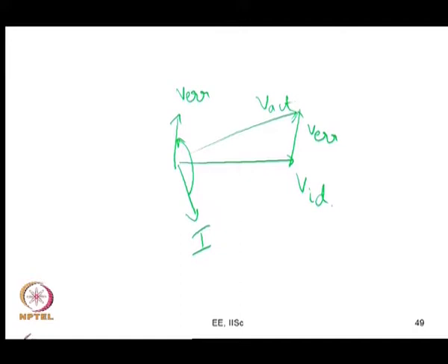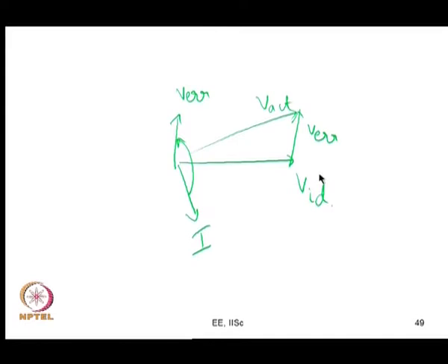What happens is there is a difference in these voltages V actual and V ideal, so this can actually be seen as an IR drop. In induction motor drives this can be seen as some additional stator resistance, and when the stator resistance is high it causes instability. Though I have not discussed it in this module, dead time also has the effect of increasing light load instability in induction motor drives, which you can find in certain papers. If you compensate for dead time, you can handle light load instability, and it becomes good.